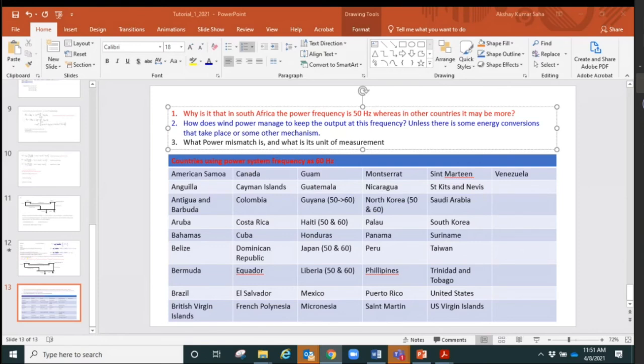And this mismatch can be P, it can be Q, it can be apparent power, MVA or kVA or volt ampere if it is a small system. So the unit will be the respective one: megawatt, megavar, MVA. You can also find mismatch in MVA capacity. Is that clear? Or do I need to say something more? If you have more questions on this, you can ask.